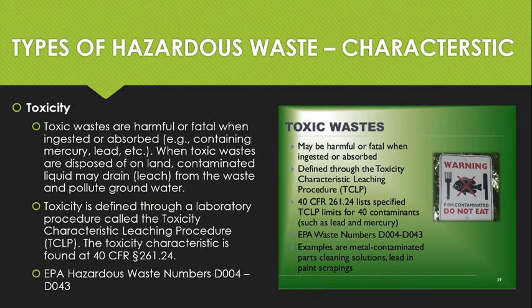And then the fourth category of a characteristic hazardous waste is toxicity. Toxic wastes are harmful or fatal when ingested or absorbed. It could contain mercury, lead, etc. When toxic wastes are disposed of on land, that contaminated liquid could drain or leach from the waste and pollute the groundwater. That is why we can't take this kind of stuff to the landfill. If I tested that poopy water earlier for metals, like we talked about, like the landfill requires, and it came back hazardous for lead, well, it can't go to the landfill. It's a toxic hazardous waste now. And it would have to go to Clean Harbors or U.S. Ecology or through Green Planet to those disposal facilities, some type of deal, because it's hazardous waste.